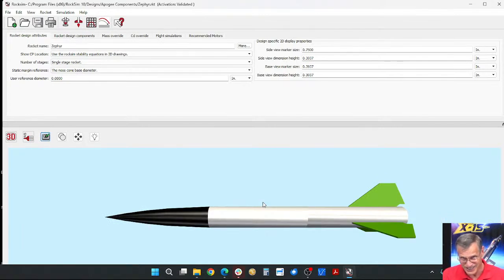Probably not. Just think of a piece of paper that's glued on top of your rocket skin. It's probably not going to change the aerodynamics at all. What other change would it affect? The other thing it could affect is the mass of the rocket. The paper has thickness, volume, and density. You're going to put some glue in there, so it is going to add mass to the rocket.